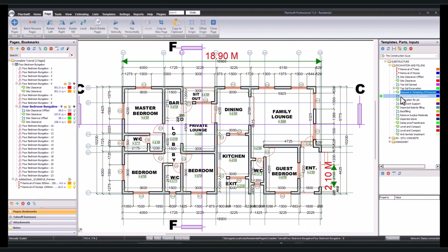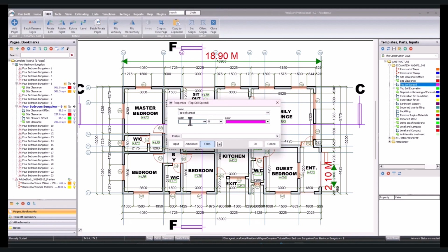So now I'm going to be creating the spread. So I'll come here, spread, activate. What's the width of the spread? Since the width of our wall is 225, I'll be using 0.225 as the thickness of our spread. Why am I putting in decimal? Because I've changed it to meter. So I might change it to mm.